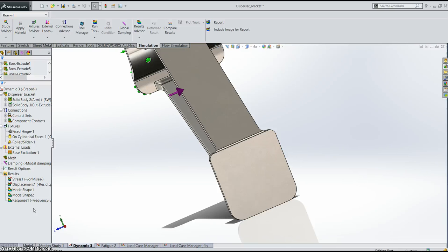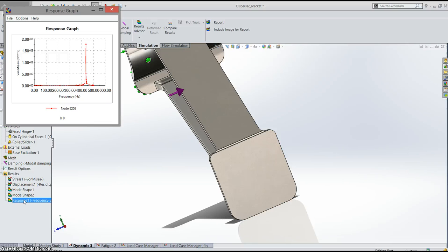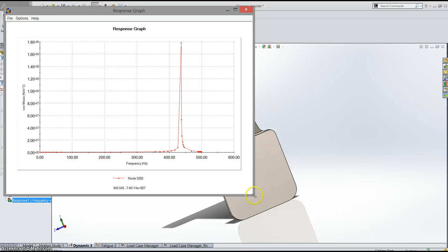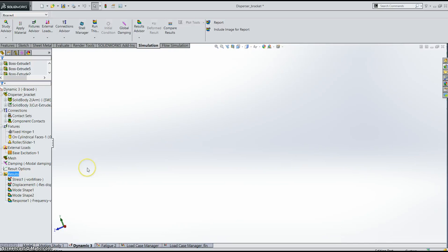When it comes to vibration analysis, durability and fatigue are common concerns. It's also beneficial to identify key characteristics for various vibration modes. So the new frequency response graph has been added to enable you to review the mass participation for the modes. So this can help in identifying the direction being excited by a particular mode, as well as the proportion. The fatigue study now supports random or harmonic vibration analysis as well.